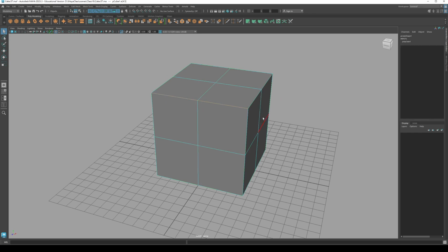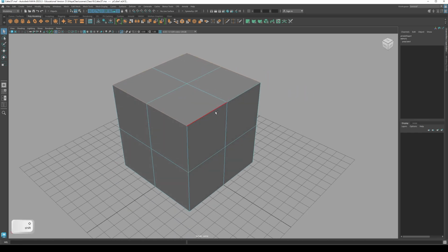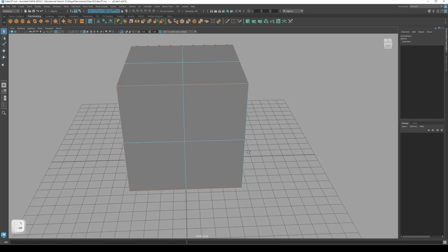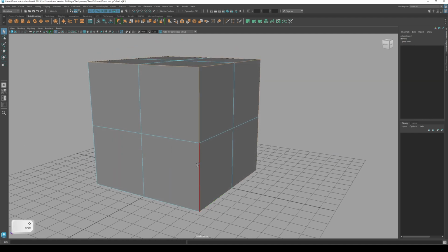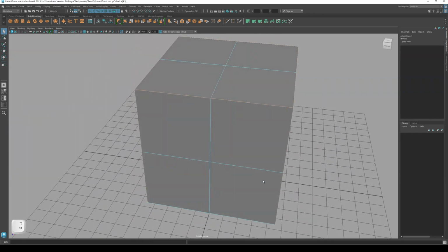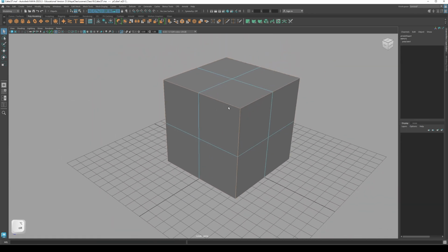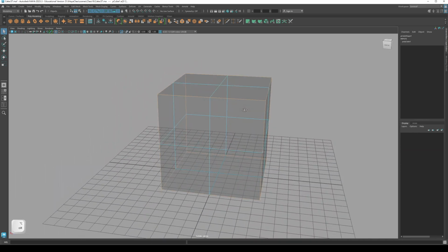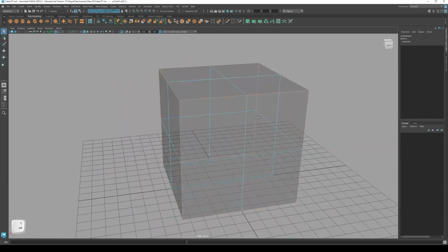Then let me add the bevel. Select the edges and then go to bevel. Let me select edge first. Did I miss something? No. Okay. Turn on X-ray mode to check if there are any edges that I missed.